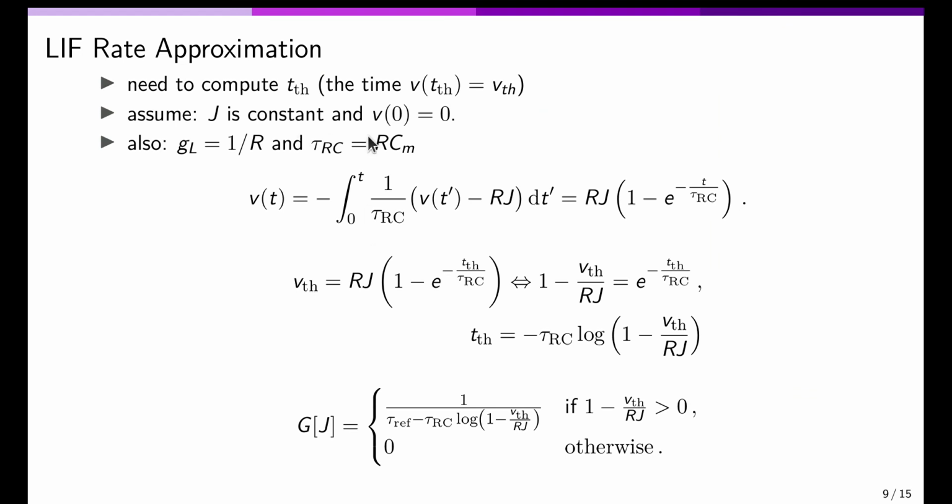There's a little bit of notation that's going to happen here. As a reminder, there are two different ways of writing how a resistor behaves: as conductance, or as 1 over the resistance. In this equation, we're going to switch it over to R, because that's a little more common. There's also a cool thing that comes up in electrical circuits all the time: when you have a resistance multiplied by capacitance, you get a time constant. The units of those two things work out to seconds. So it's really common to collapse those two things down into a time value, because that gives us intuitions about how quickly the system is going to respond and behave. Those two identities get tossed in here. Other than that, we take the equation from the previous slide, do those substitutions, and we get this thing here.